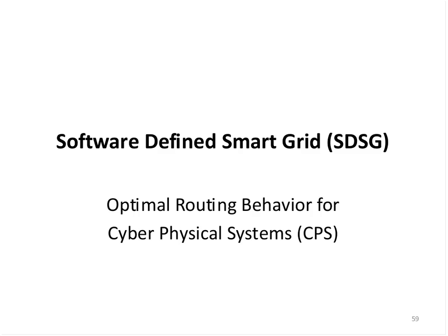The weight of the protocol, and by the way, there are servers out there that can do 240,000 concurrent connections and 60,000 messages a second, as well as clients that can get down with a full TLS library to 89K flash and about 40K RAM. Without the TLS library, it goes smaller, about 30K flash.